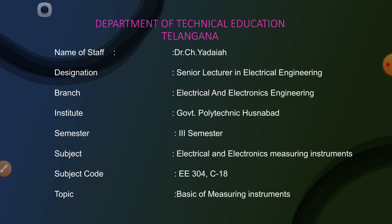So, this controlling torque can be produced in the instrument by using two methods. One is the spring control method, another is the gravity control method. In the spring control method, we use phosphor bronze spiral hair springs, two of them, on a spindle.